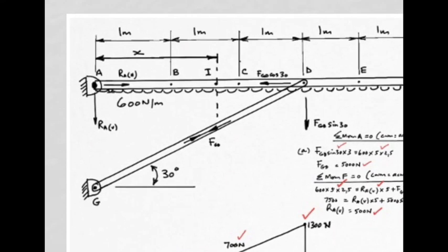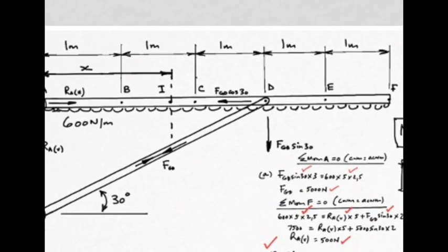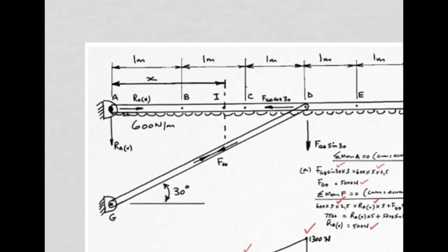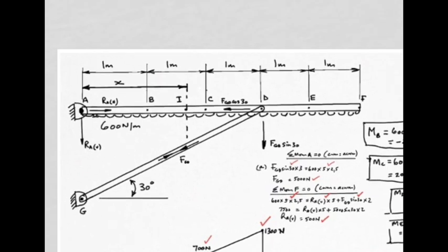Working out the force in the lift strut, remembering that it will be a tension member. Remember, 2 arrowheads towards each other. So we'll call that FGD, G to D. And when we come to use it on the actual beam, let's use components of FGD. And we were told that there's 30 degrees there, which means there's 30 degrees there. So FGD rotated through 30 degrees would give us FGD cos 30 down the spar, or the beam in this case, and the other component FGD sine 30. So those are the ones that you're going to use when you take moments for the actual beam itself.